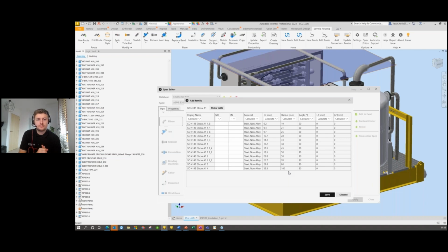And we use point clouds and meshes to kind of drive our designs. So we want to show an accurate route, and rather than just 90 degrees and straight, we want to show exactly how it interacts with plant. And sometimes a fall over a long length makes a big difference to the clash detection. So we would use that quite a lot.